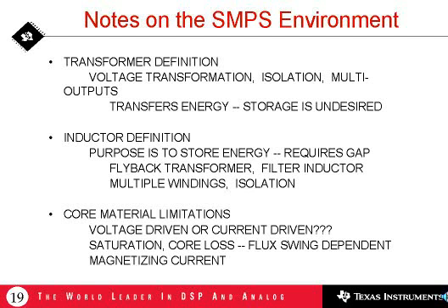Now, a filter inductor is obviously an inductor, but a flyback transformer, even though it's loosely called a transformer, is really an inductor with multiple windings. And it does have transformer-like properties. You can have different turns ratios and step voltages up and down, and you can achieve isolation. But unlike a true transformer, the flyback transformer is fundamentally an energy storage device, and it really falls under the class of inductors.